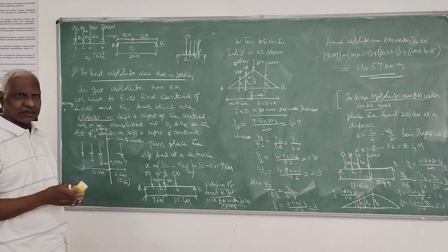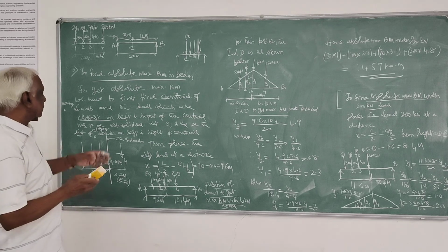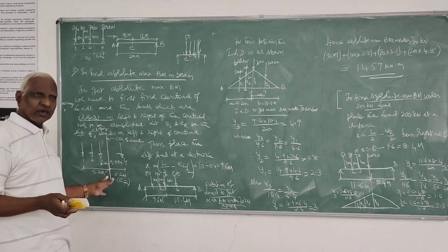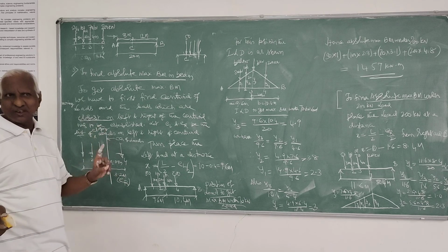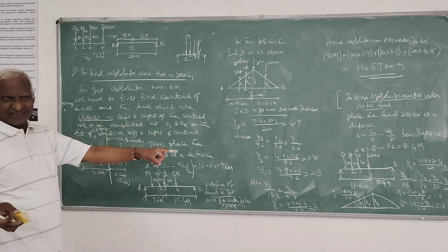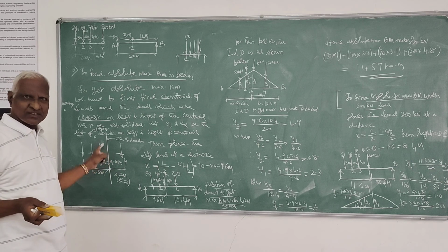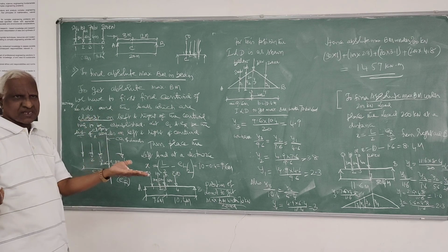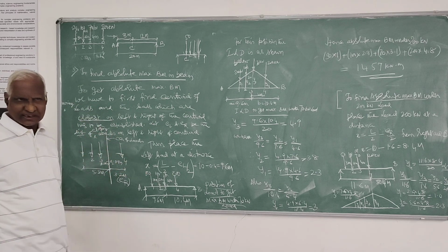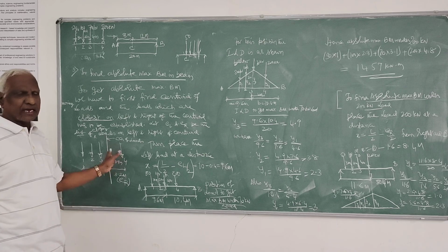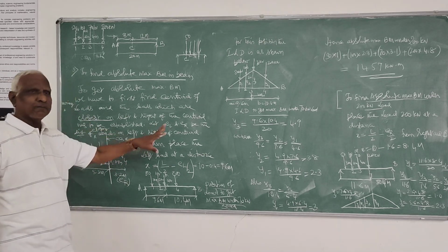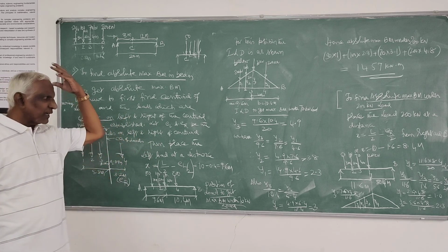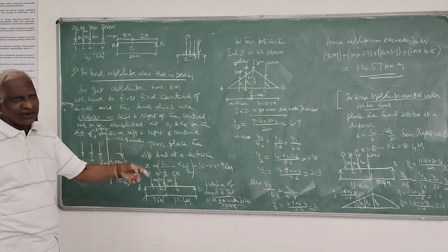Though the book states that the absolute maximum bending moment occurs under the load which is closer to the CG of the loads, that is not happening here. Though the 70 kilonewton load is closer, it is happening at the 200 kilonewton load. That's why I told you to do the calculation for both loads, on left and right, as that is always safe. If they are of the same magnitude, then you can just write a line saying so, and the maximum occurs at the nearest load.